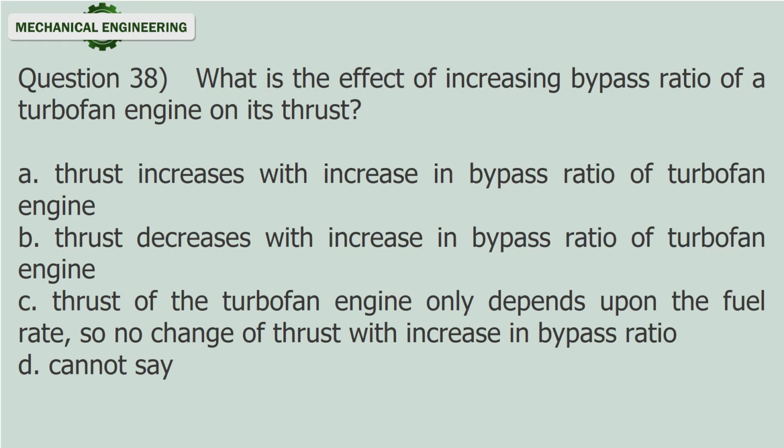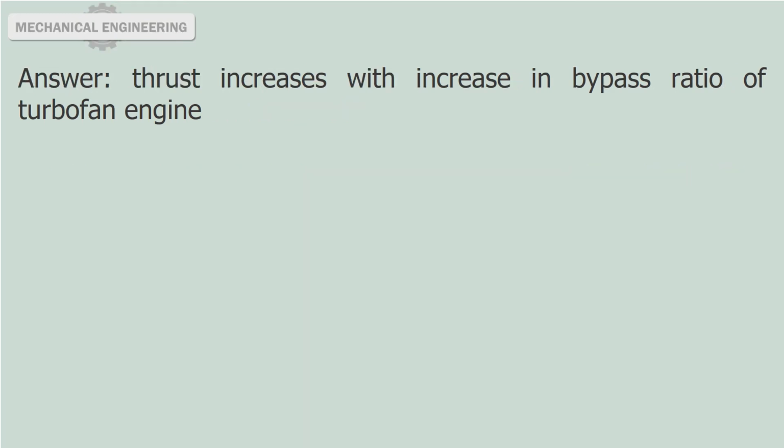C. Thrust of the turbofan engine only depends upon the fuel rate, so no change of thrust with increase in bypass ratio. D. Cannot say. Answer: thrust increases with increase in bypass ratio of turbofan engine.